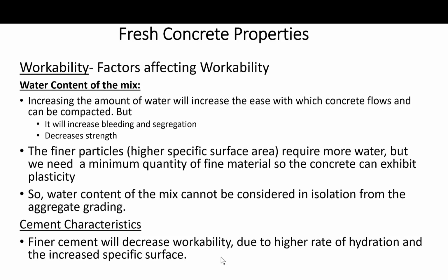Okay, so with regard to cement characteristics, it's known that the cement characteristics are much less important in determining workability than the aggregate properties. But the increased fineness, for example, of the type 3 high early strength cement will reduce workability for a given water cement ratio, as these cements have higher water requirements because of their higher specific surface area and because they also hydrate more rapidly.